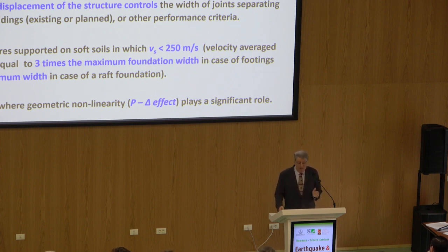It is mandatory when increasing the fundamental period increases the spectral accelerations. Only for very tall buildings, 20-story or more in Bucharest, you don't have to take it into account. But for such important structures, you will take it into account because the displacements are important. Anyway, when displacements are important for joints separating, when the structure is founded on very soft soils, when P-delta effects for tall structures are very important, in these cases, you should.